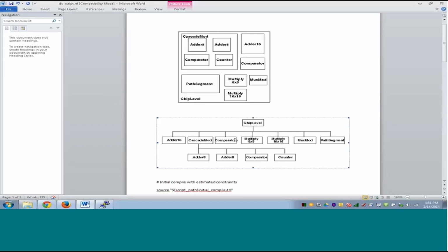And now at chip level, I will not even read the complete design. I will read the chip level, but now I will read a Verilog file which is generated from, let's say, the CPU. There will be a CPU netlist, but from this CPU netlist I will generate one more file using some script or some tool that will only contain the CPU module definition with inputs and outputs and nothing else. So it's a black box CPU.